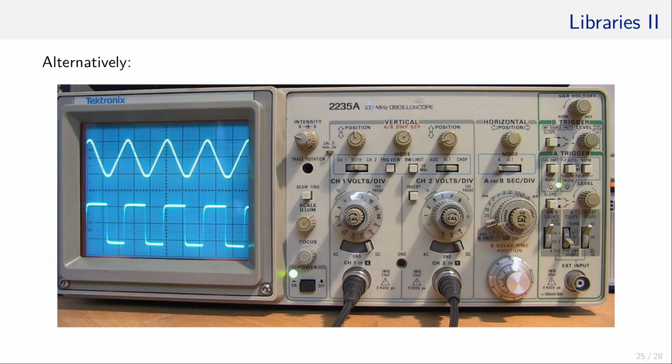Nevertheless, in the exercise, you have to implement the DHT protocol, and I provide the binary to convert the ATmega into a simple oscilloscope. Please note that this oscilloscope is by no means comparable to the commercially available ones. Its sample rate is around 76 kilosamples per second. Even the cheap oscilloscopes have multiple megasamples per second. 76 kilosamples per second means that this ATmega oscilloscope takes a sample every 13 microseconds, which is too slow to debug 1-Wire. However, for DHT, it is just enough.